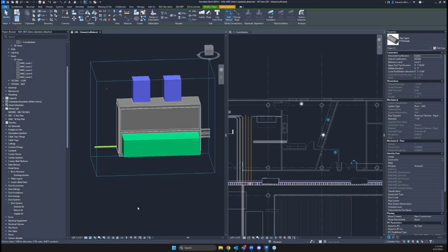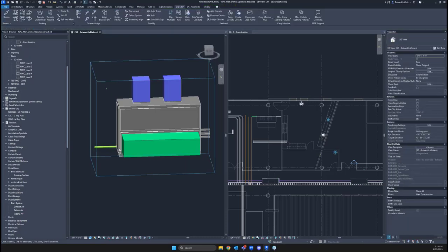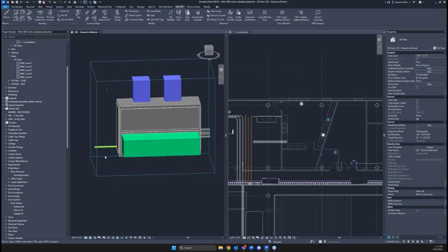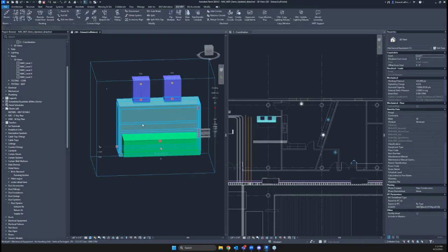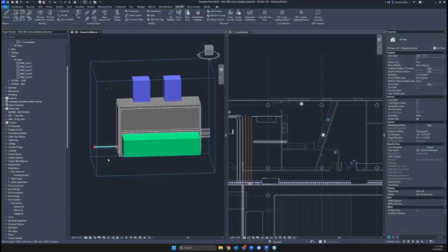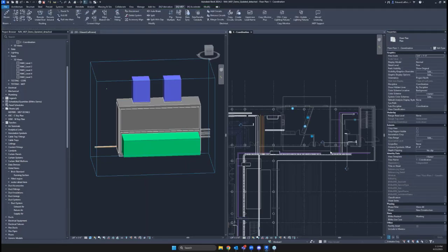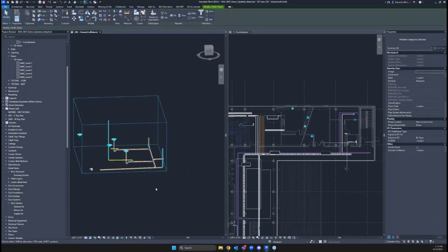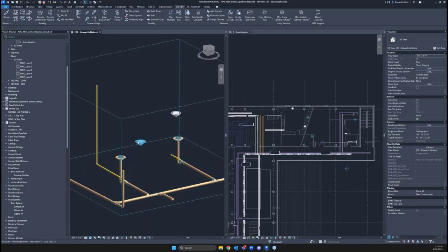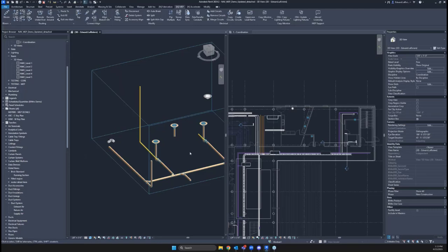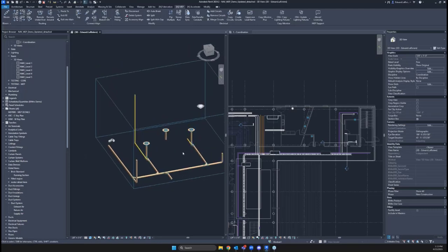we should find, oh, I want the drainage system type, not the sanitary. You can know where every button is, but you can't fix user error. There we go. Now we'll see I am getting that correct type coming out of the side over here. So let's jump back to the underground, grab some elements, bring us back to this area, and we'll find that that now lets me go direct to that floor drain, use the bloom command, which I keyboard shortcutted, and immediately have that stub ready to go.